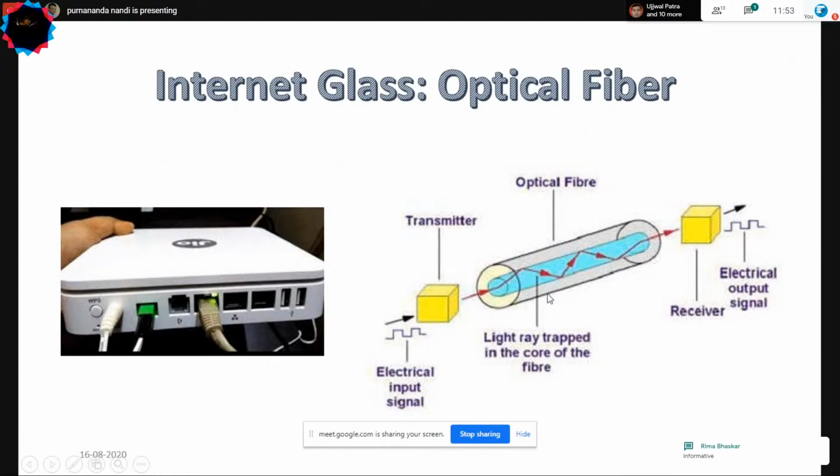See, this is an optical fiber. It's shown in a very crude way, but I will show you the fiber later on. In the design of the fiber, you see there is a blue color core in the middle, and there is a cladding outside. Both are glass. It's amazing technology, how they can make two different refractive indices inside the glass. The reason for making the refractive index variation is to make the light go through total internal reflection inside the fiber, so there is no loss.